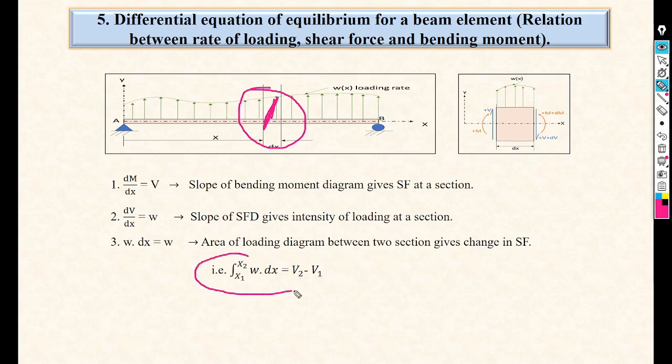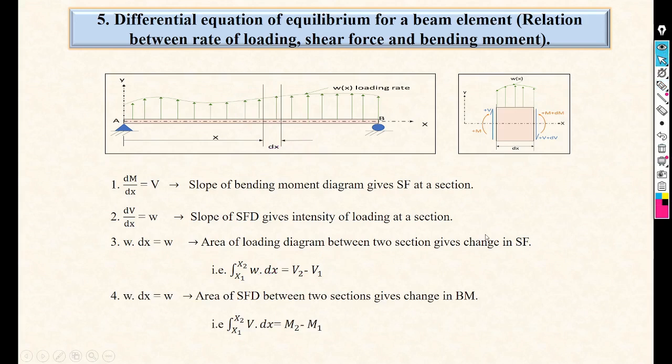And this is the general formula. If we take the integration of w with respect to x, we get the difference of the shear force. Same thing: if we take the integration again, the area of the shear force diagram between two sections gives the change in bending moment.